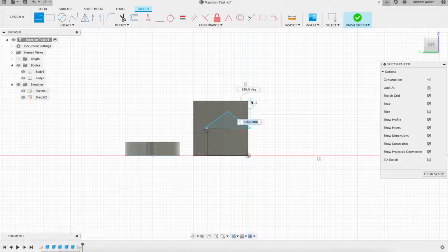And then let's do the same thing for the roof of the house. So I'm going to start on the corner of the roof. I'm going to go 1 away. I'm going to go all the way to the other side and go 22. So it's 1 over on both sides. Then I come up to the middle. And let's say my eccentric billionaire wanted a very specific angle in his roof. Say he wanted an 18-degree angle in his roof for whatever reason. So I'm going to hit tab to the degree area, and I'm going to say 18.